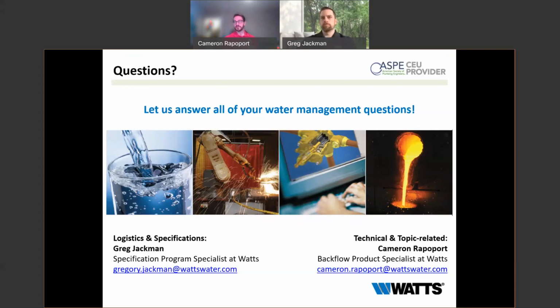And if it's submerged, it's going to be siphoning water from a pit that shouldn't be installed in back into the drinking water. So I would say that's the big difference there, a manually operated valve that's normally closed and should only be open for testing versus a relief valve that's going to be opening and closing just based on hydraulic circumstances.